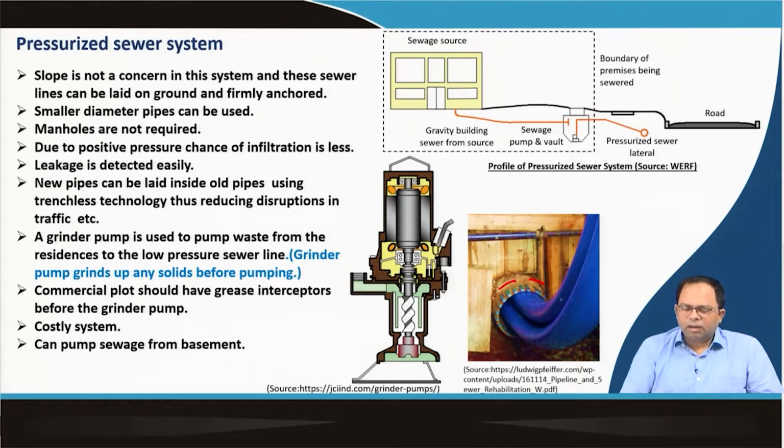and because as you can see the conduit would now be smaller in size, this could be a pressure conduit. So, instead of using the old conduit, if there are certain issues with it, the blockages, chokages and all, we clean those things and then we put in a new line, as you can see in this one, which could be under pressure. Because it is a smaller pipeline compared to the earlier one, and because it is under pressure, it should not be any problem. That means, for the quantity that we can send, we require a lesser diameter pipeline in that case.